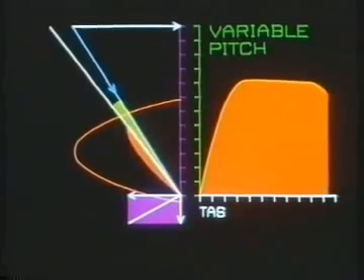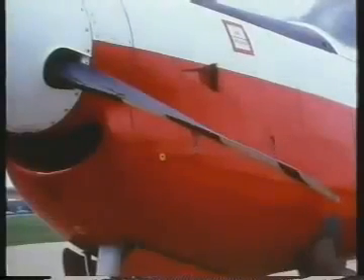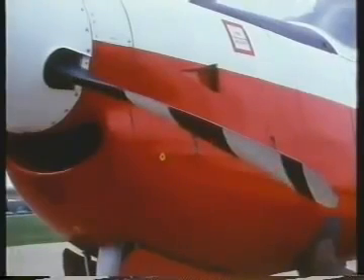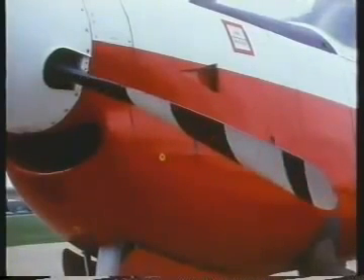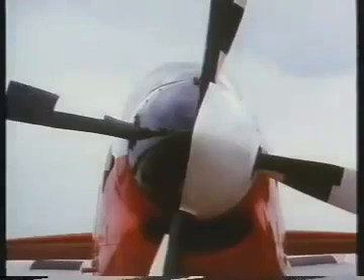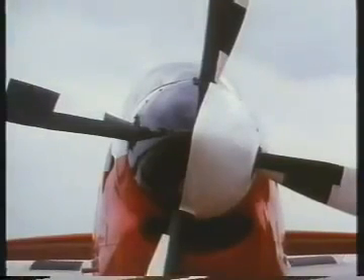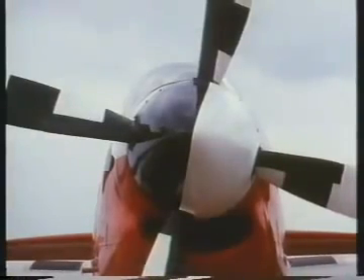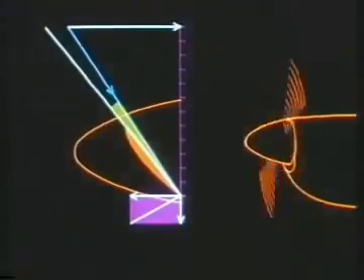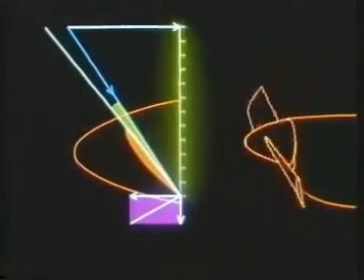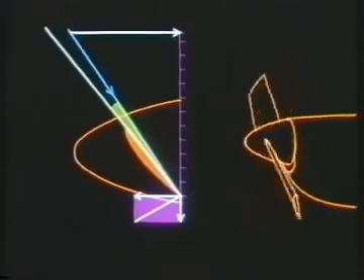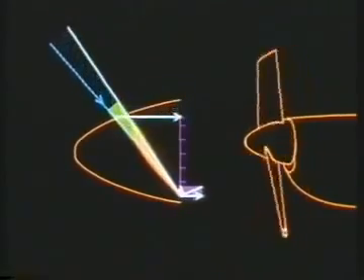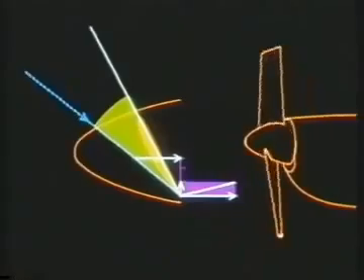With a variable pitch propeller, a constant speed unit automatically adjusts the blade angle to maintain a constant loading on the engine. The selected propeller RPM remains the same, regardless of engine power variations and airspeed. However, a potential problem was created. If the engine failed, the rotational velocity would start to decrease, and the constant speed unit would reduce the blade angle to try to maintain the RPM until the blade reached the fine pitch stop.